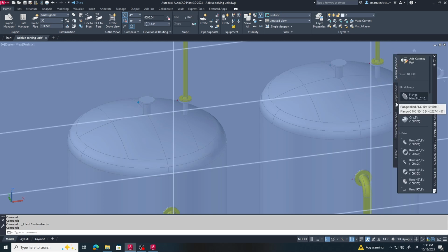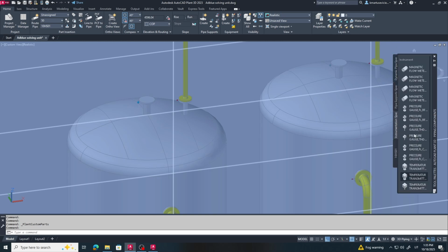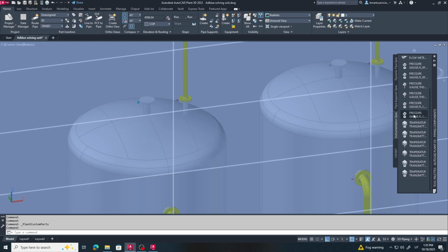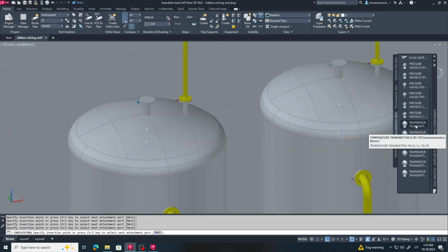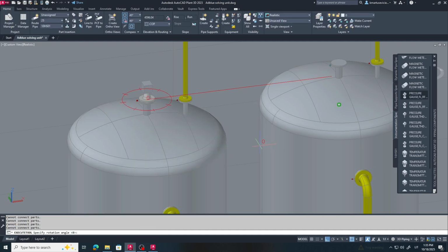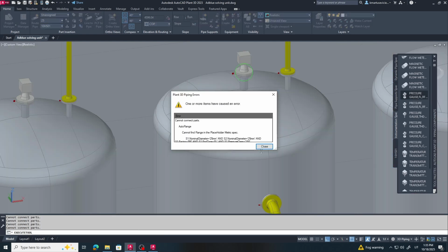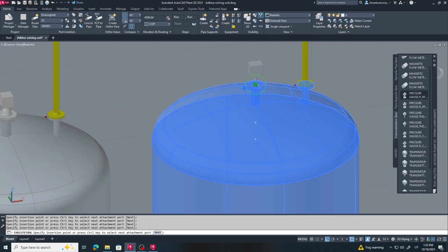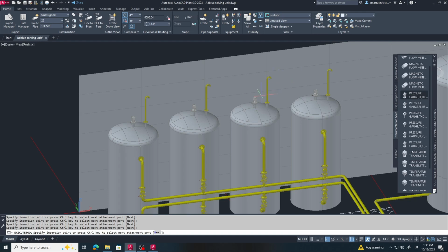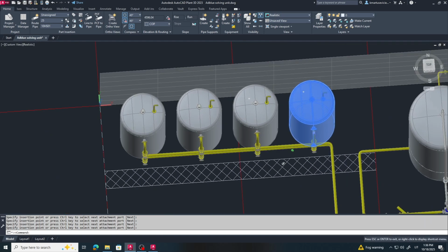Now it's time to add the level sensor. In our case, this is a level transmitter, not just a simple indicator. A level transmitter continuously measures the liquid level inside the tank and sends an electronic signal to the operator's control system or monitor. This allows the operator to see the exact tank level in real time, get alarms if the tank is overfilling or running empty, and automate pumping or filling sequences. Level transmitters are much more reliable than visual gauges because they work even when the tank is closed, insulated, or not accessible.